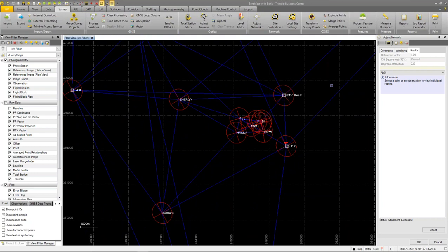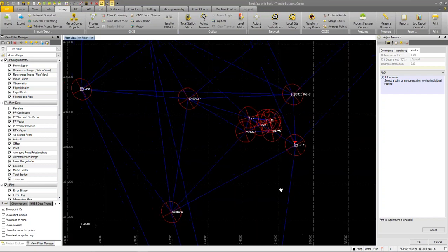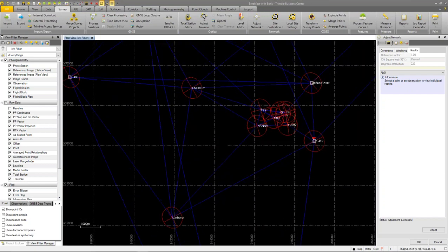If you want to do a big control net and report ellipsoid heights in the end, then you would constrain ellipsoid heights. That's a little more rare, but sometimes if you're part of a big government agency, that may be what you finally report to customers and let them use the geoid to derive elevations. It's up to what you want to provide in the final coordinates for your project. So in that case, you were fixing the elevation above the geoid, not the height above the ellipsoid, just to be clear.